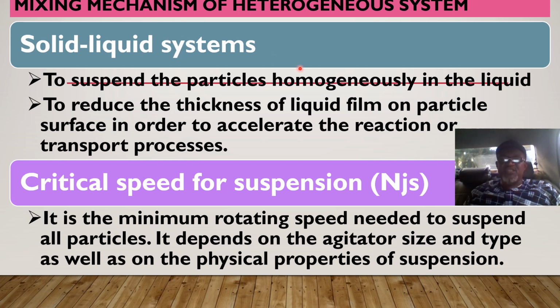We also have solid-liquid systems. Now, the aim is to suspend the particles homogeneously in the liquid, to reduce the thickness of the liquid film on the particle surface in order to accelerate the reaction or transport processes. Like we said, it might be for chemical reaction, it might be for transport processes.